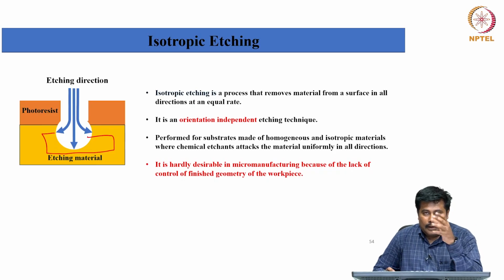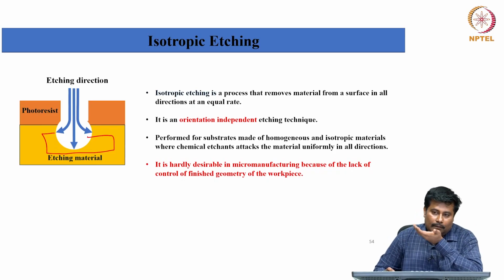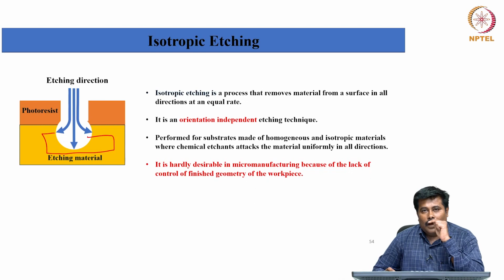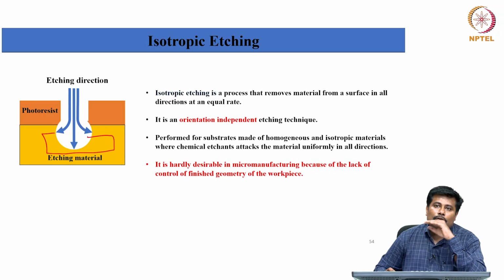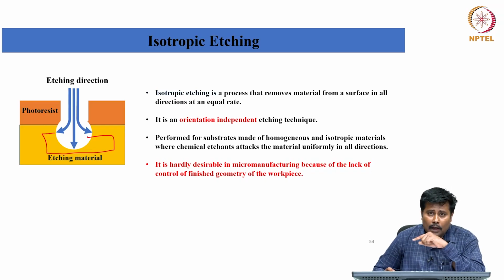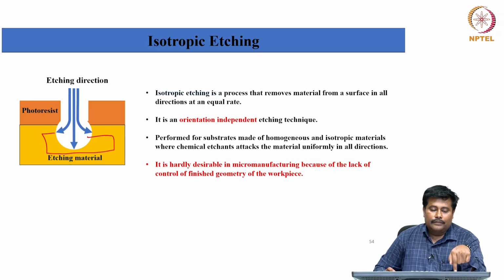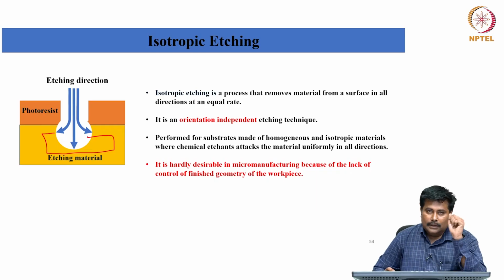And yes, in certain cases, for example wherever we have single crystal structures, such isotropic etching may have an impact. In the case of single crystal etching, these wet chemical etching methods will have an impact on the overall crystal structure, which can be efficiently eradicated using a dry etching process.